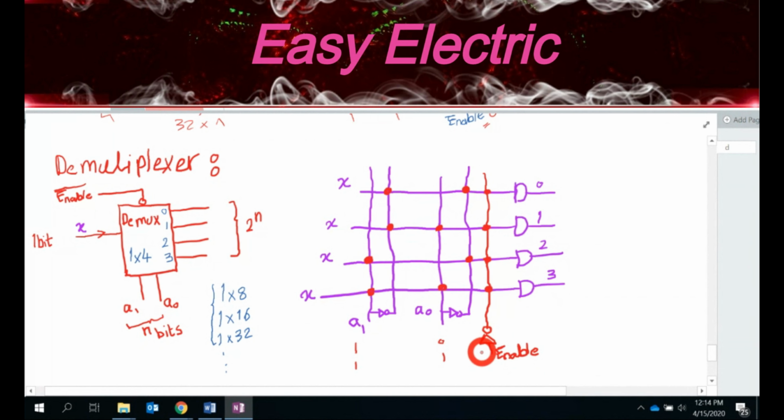So see as it works, that's what we expect. Whenever this is 0, which is active, NOT is 1, and that means this AND has 1, 2, 3, 4 inputs. One of them is 1. If you have a 1, it actually does nothing on the AND, right? Because 1 AND everything gives the same thing, has no effect on the output, okay? So that means it should be right. So whenever this is 1, the NOT is 0. That means one of the inputs of this AND is 0. So no matter what you have in the other inputs, the output will be 0.